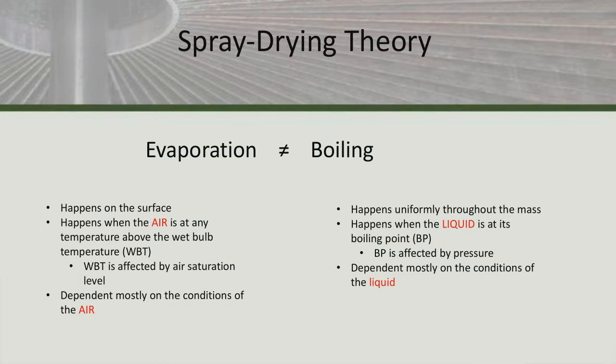Now, a lot of people are concerned about spray drying when they have temperature sensitive products. And this is a valid concern, but in my research, I found that I'd say maybe 8 times out of 10, it's not as big of a concern as either I or the customers expect going in. And this is because the temperature that the material experiences is significantly lower than the temperature that the drying gas is set to at both the inlet and the outlet of the dryer.